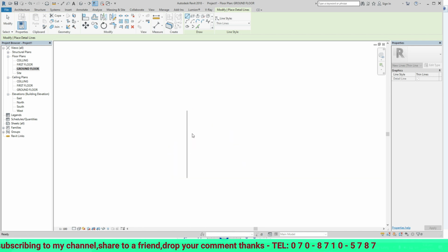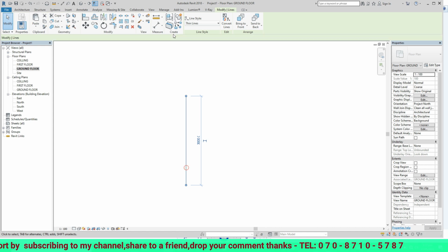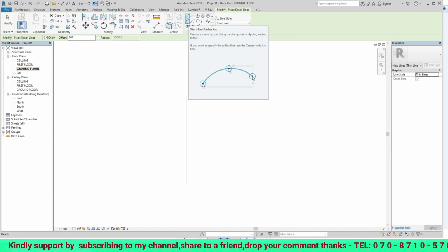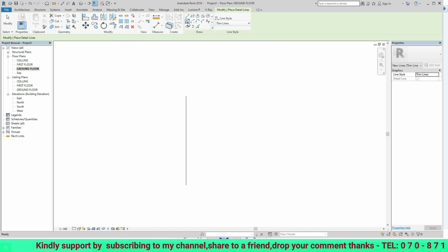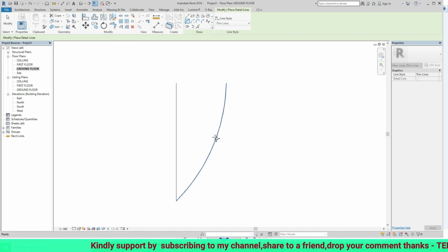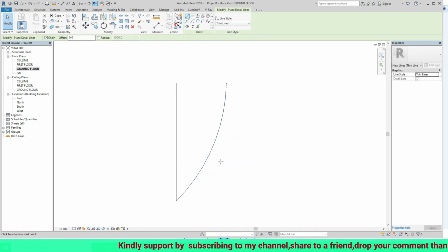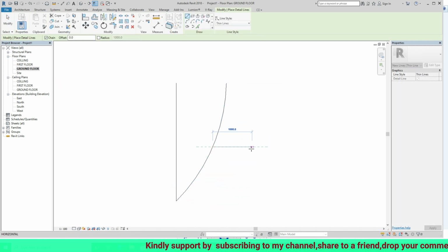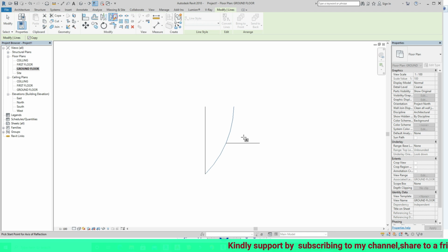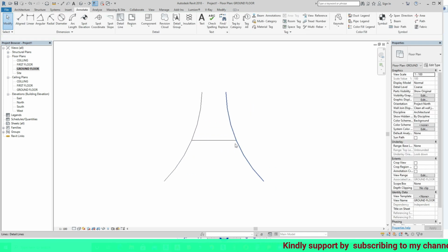3000. This is the height of my building. I'm trying to use line to create the different kind of stair I want to use. This is the width of my stair, 1500 mm. Let's mirror this one, so we can delete this and this.